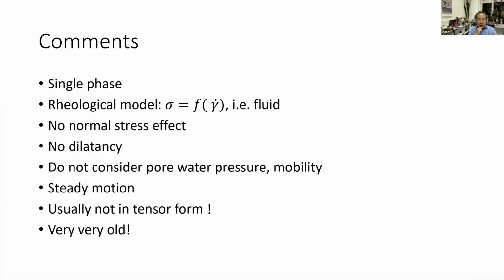And I would like to recall a similar analysis in geotechnical engineering. We call it total stress analysis. It was just before Terzaghi proposed the principle of effective stress. But even today, if you look at the practice, this kind of single phase is still used. You think about total stress analysis, undrained analysis with undrained strength. It is still very popular. I mean, the existence of such a model certainly has its justifications, right?